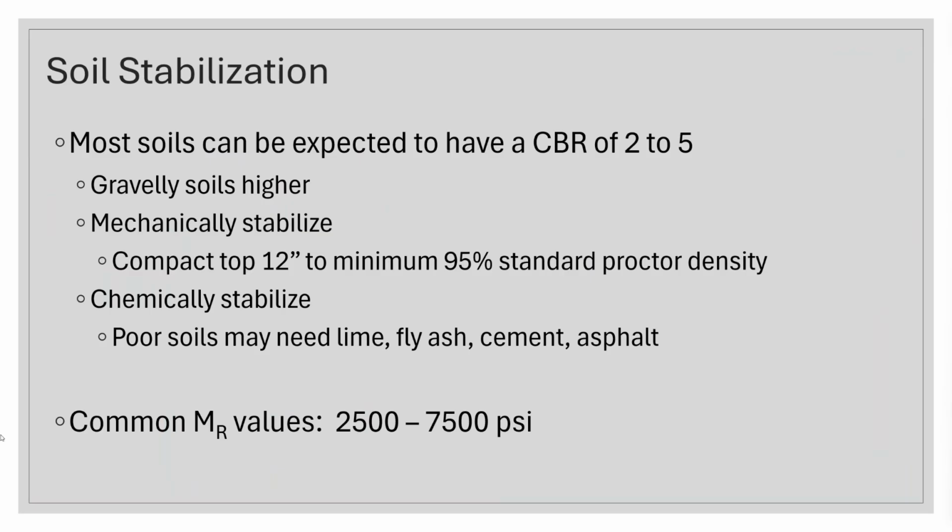But that action of creating that additional compaction, we're mechanically stabilizing, we're trying to do something to that subgrade to take it from its natural condition and make it a little bit stronger. So we pack it nice and tight so it's really solid, gives us some additional stiffness to work with when we go to put the base and surface layers on top.